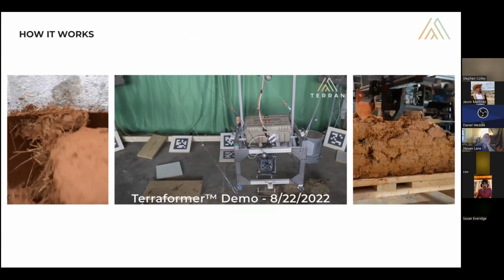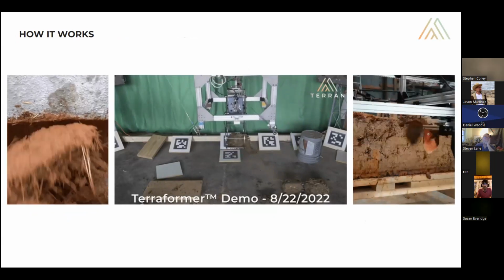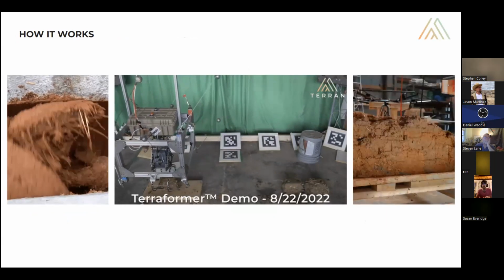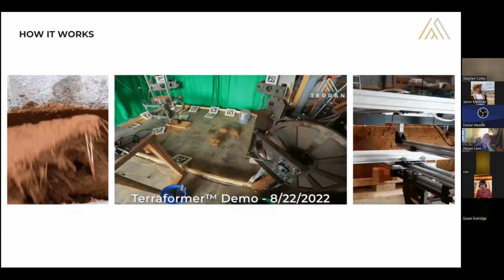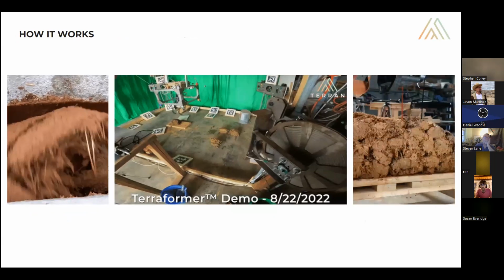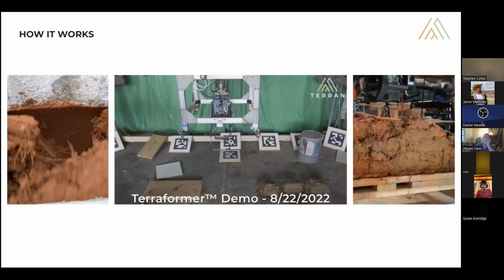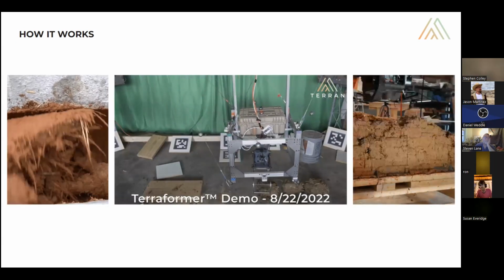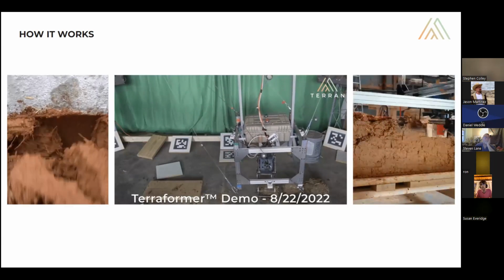It's 4 corner posts, 2 lines to each post. It does pick and place through vision, and then it does a tool swap. And that final tool you see on the right side reads the topography of the wall, goes through and smooths it to a single plane. It does that on all sides of the wall, top, and then the 2 long sides, which is a fairly simple optimization problem.